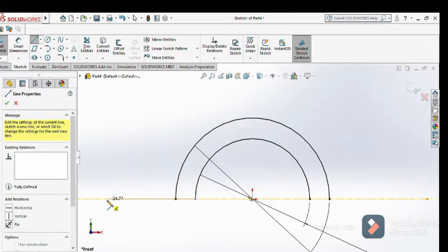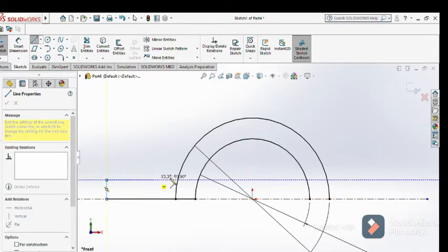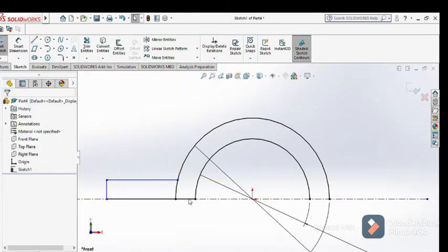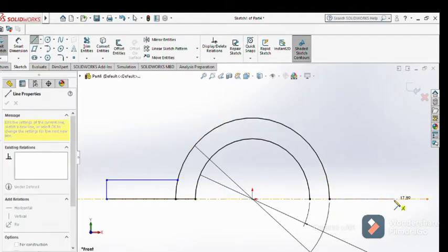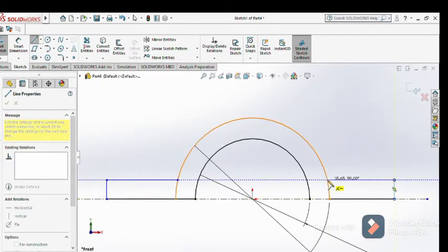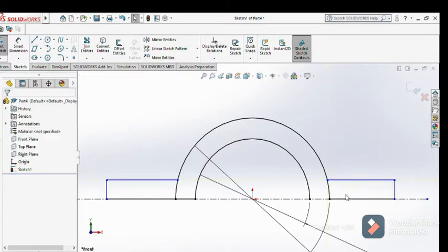And then go there, and it comes back there, and it ends up with the bigger circle there. Then you press exit to cancel the line. You click line again, you go there, there, and there, and then you press exit again to cancel the line. After that, you use trimming again.